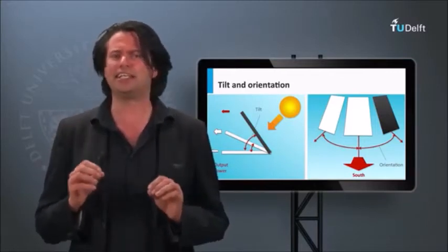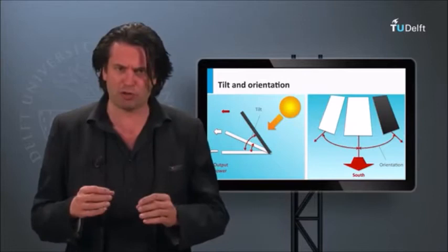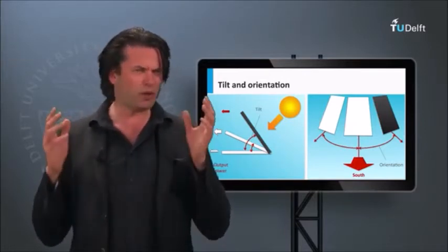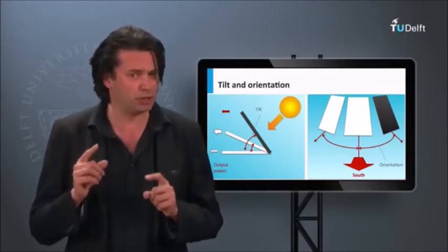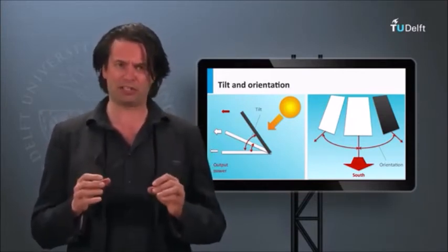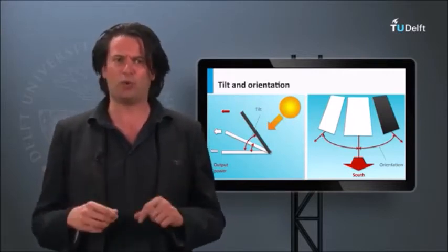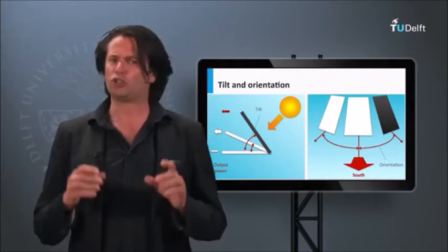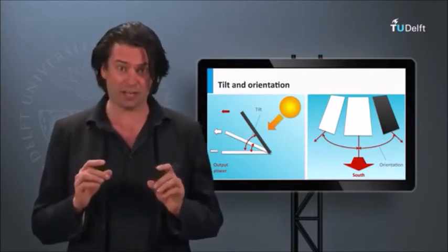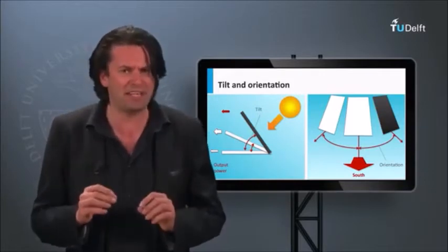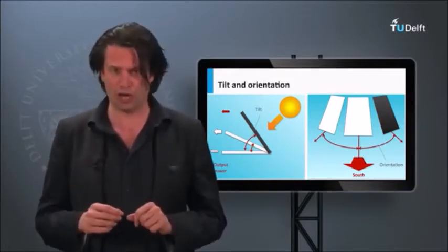Hence, the need arises for the concept of an optimized orientation and tilt. What do I mean by this? As the majority of PV systems have fixed mounting of panels, designers have to live with a single orientation and tilt throughout the year. So what should these fixed angles be? The answer would change depending on the geographical location.